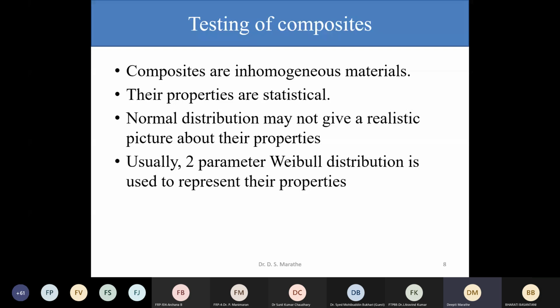I am going to make the composites by various different methods. In the previous lecture you tried to understand what pultrusion is and the other methods for making composites. Now, if I do not have all the glass fibers or the other additives in the composite well mixed, then I'm going to get pockets where there is a greater concentration of a particular additive and a lesser concentration of the other additives.